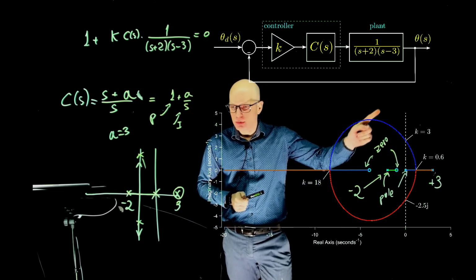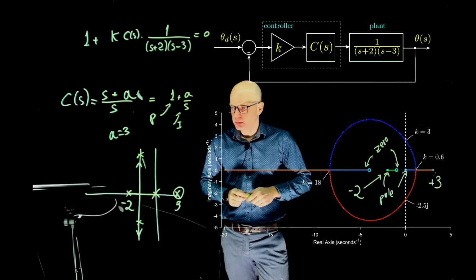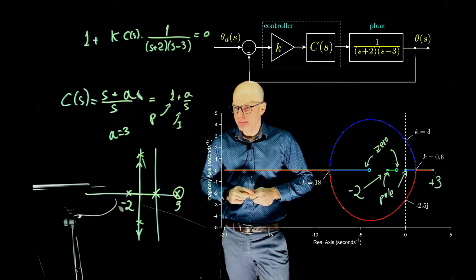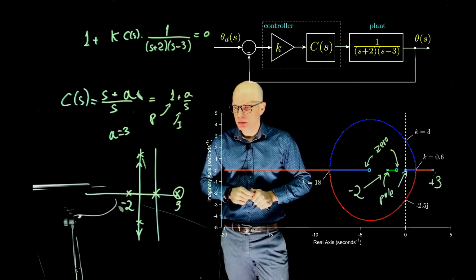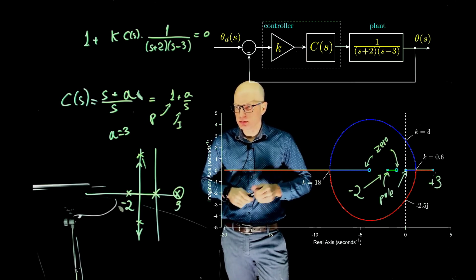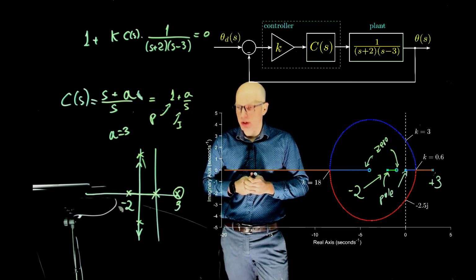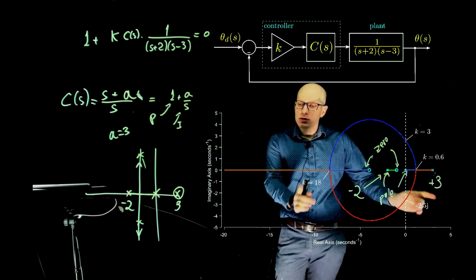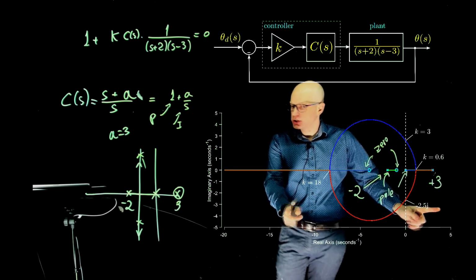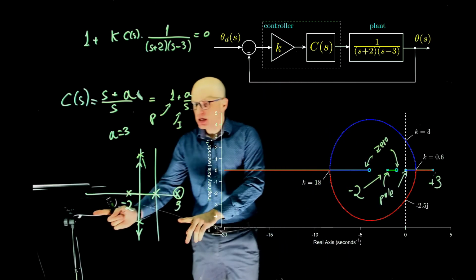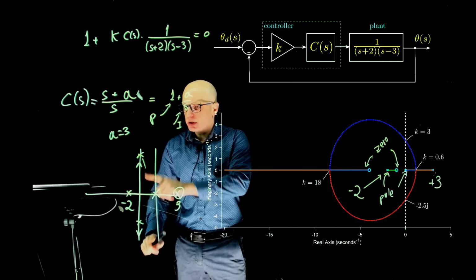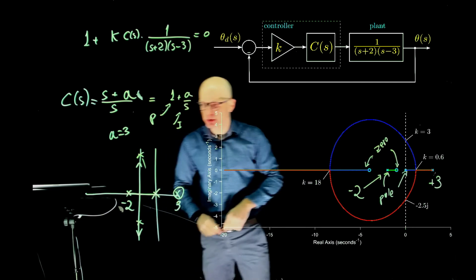The PI would oscillate till infinity, but with the PID controller, when k is 18, as k tends to infinity, it's overdamped. Right, so good point. When this k is very large, it's just overdamped. When this k is very large, we are tending to infinity here, it is underdamped.